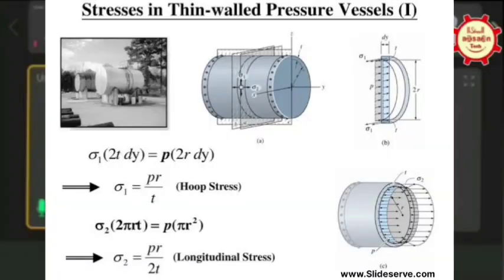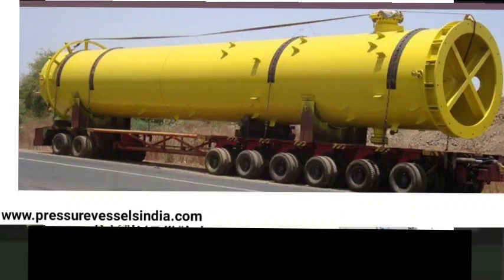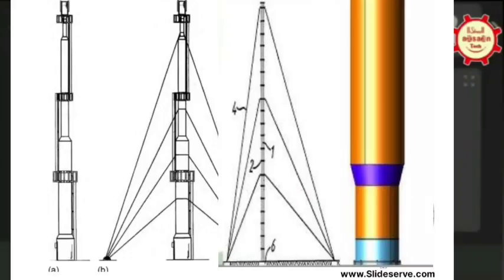One FEA person. I mean, actually, how big is the vessel, Himanshu? Actually, it is a thin-walled vessel, quite long, a column you can say, not a vessel. Horizontal column, yeah. Yes, a vertical column actually placed horizontally during the transportation. Oh, okay. So you want to analyze only for transportation? See, for transportation, we assume that it won't be a much governing factor because after that the vessel is going to be placed vertically.